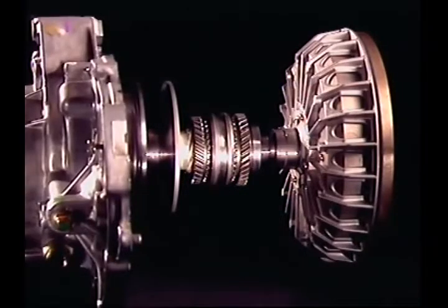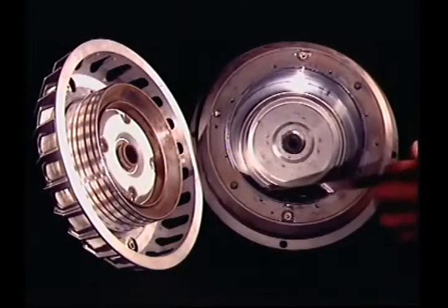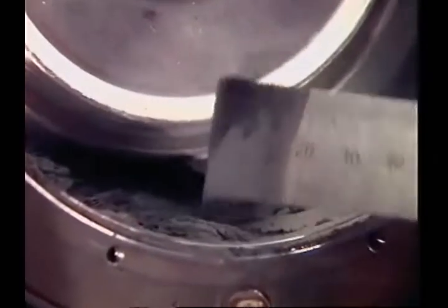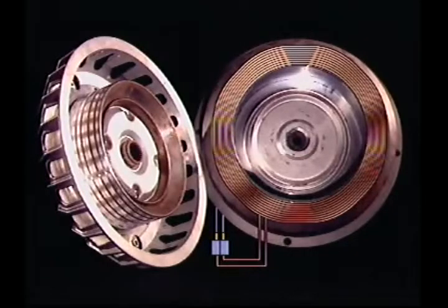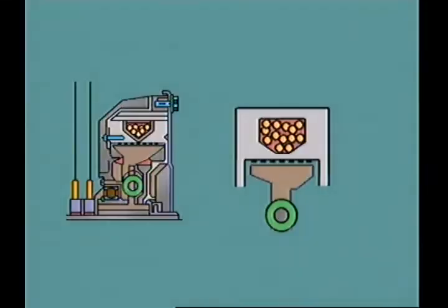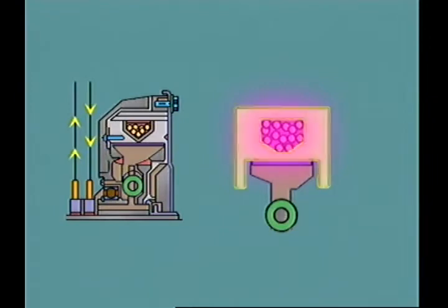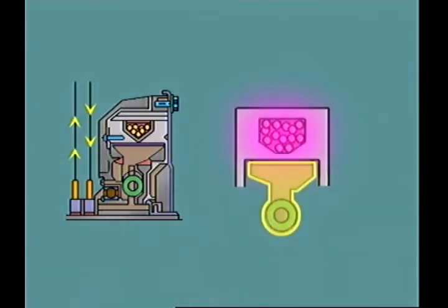This application has an electronically controlled magnetic clutch. A small gap between the driving and driven members is filled with magnetic powder. A coil on the driving member receives electrical current via 2 slip rings and brushes. Current through the coil generates a magnetic force that links up the magnetic powder in a chain fashion. Torque is transmitted from the driving member to the driven member.